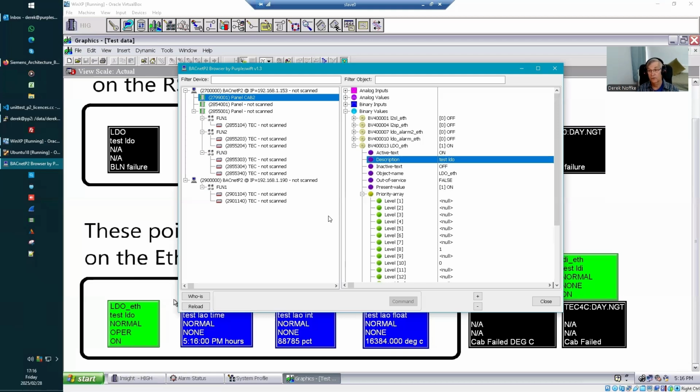And so if you want to turn on and off the devices on that floor, you switch the zone to occupied or not occupied. And we give you the zones. So we map the zones into the database from the database to BACnet. So you have the same ability to switch the whole floor on and off as the Insight system has.